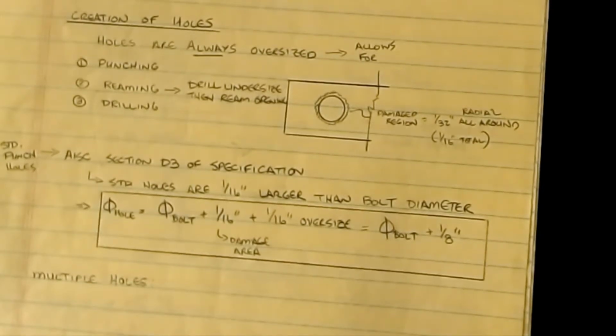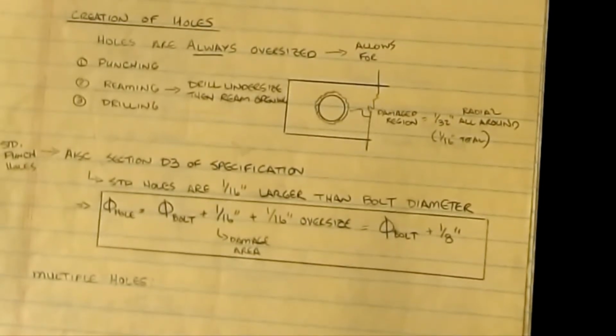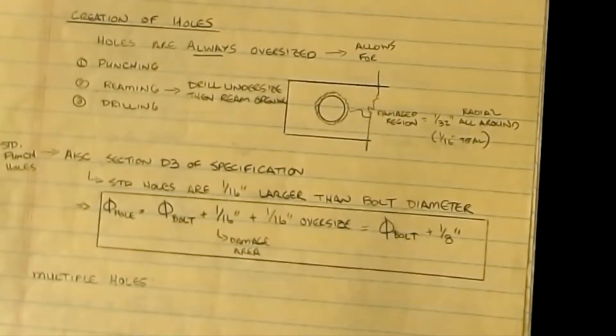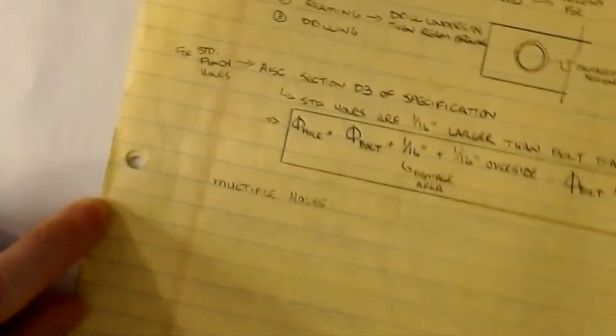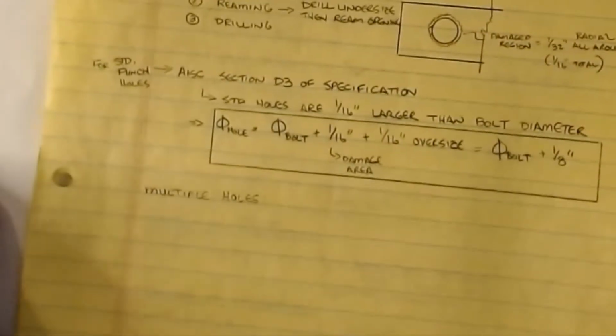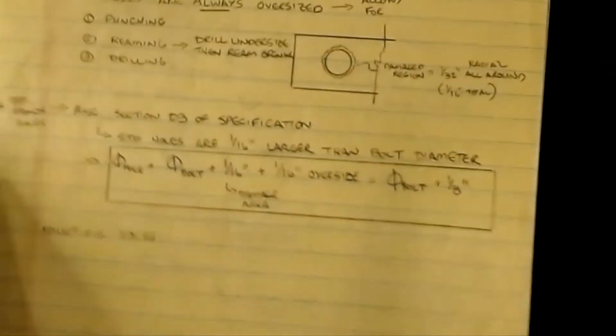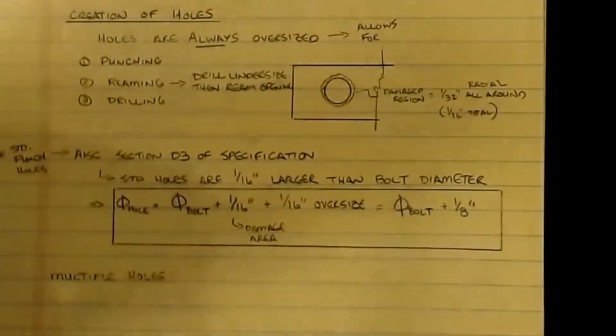And so a lot of times when it comes to making holes, they do something like a punch. Okay, if you think about the old paper hole punch, you put the paper in, squeeze the trigger, and out pops the little paper ingot that makes the hole. You can see a couple of them here. That's how I made these holes, right? Okay, well, that's a shear process versus a drilling process. And so how you create the holes is actually something we have to consider.